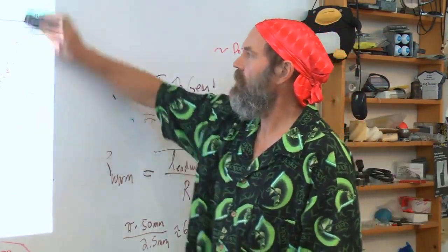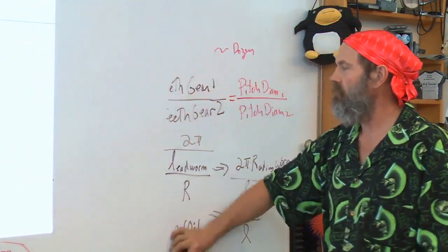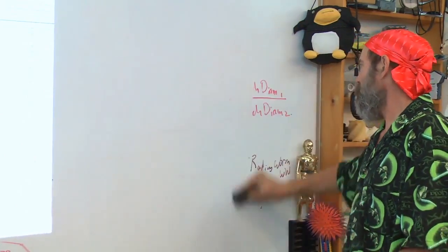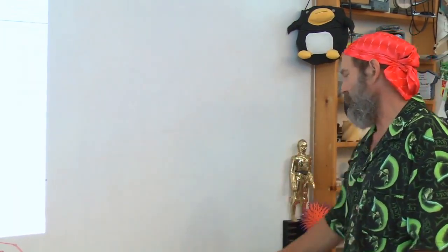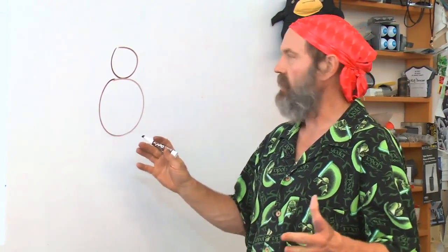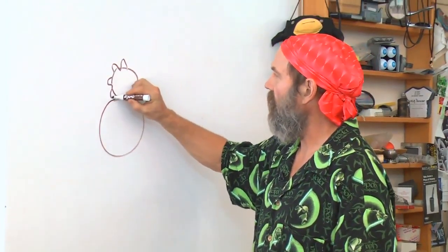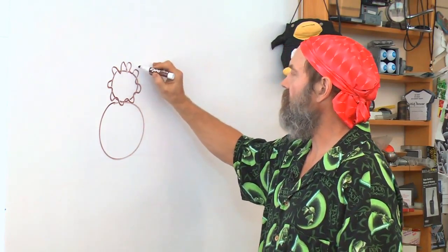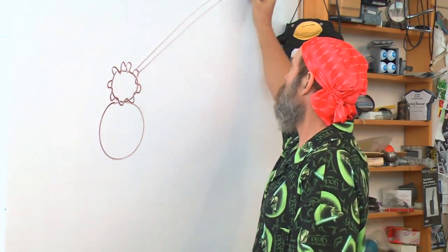Now, when you go to design your own gearbox, how do you pick all your parameters? Basically, not just the transmission ratio, but you have to be worried about the size of the teeth, the pressure angle, the width of the tooth. You can't arbitrarily pick a really wide gear to support a huge load, because if the gear teeth aren't aligned properly, they'll edge load and break anyway. So for example, if I thought I wanted to have these two gears and I want to have a huge load transmitted, and I'm worried, how wide do I have to make the teeth so they don't break off? And if it turns out they need to be this wide,